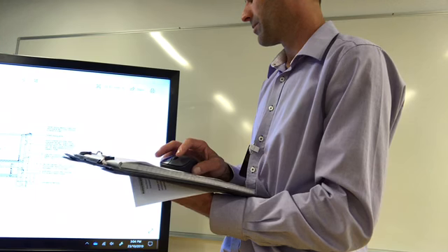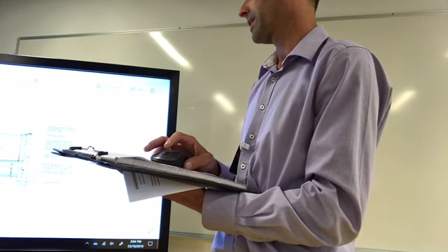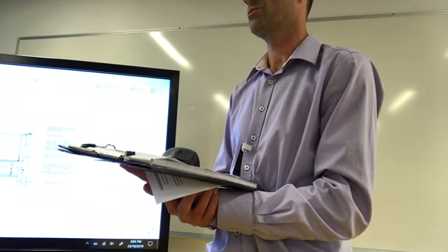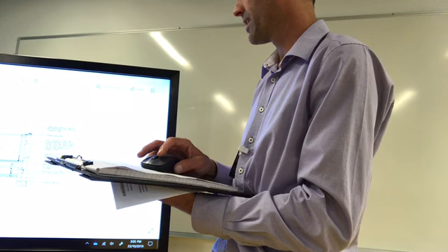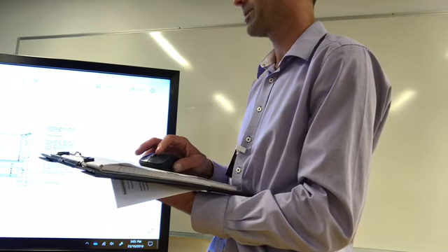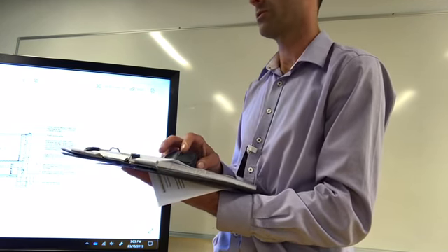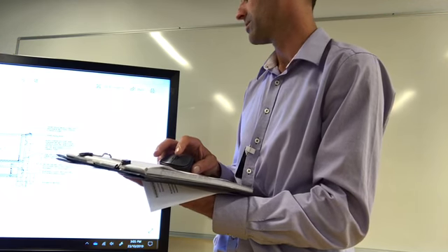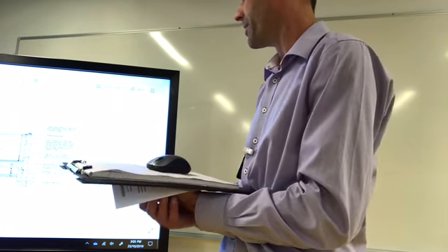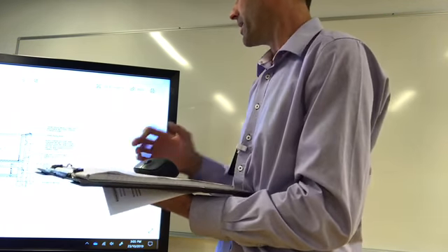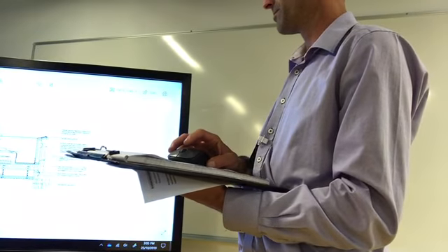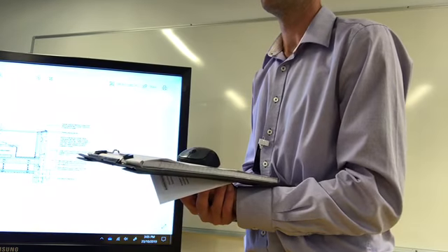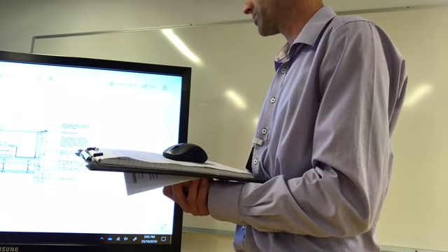And so, yeah, but with your... Yes, I guess the same principle applies with your parapet flashing there as well. And then you have to have a parapet capping over top of that as well, to lap over top of that flashing going into your gutter. And then whichever walling system you've chosen for the external of your building, and how you're going to include that on there.